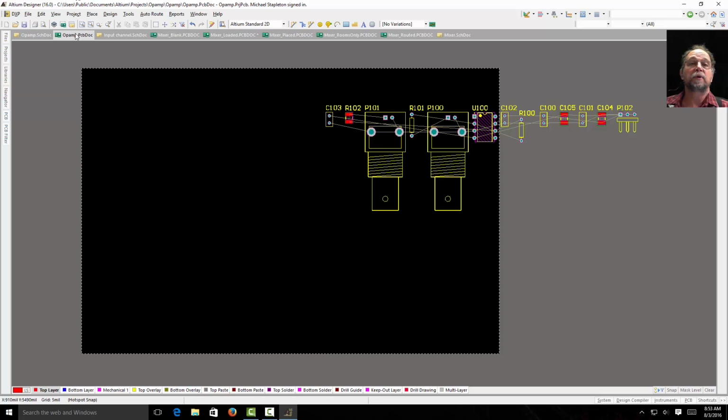So let's talk about how we're going to set up our PCB. The PCB, this area that's black, is the default size of our circuit board. And you'll notice right down here in the bottom left, I have numbers here that tell me where I am on my circuit board. And if I look here, the bottom left, I'm basically at X equals an inch and Y equals an inch. I really want that to be my 0 point.